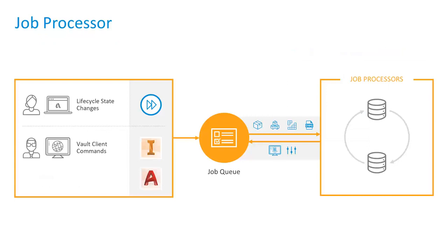The job processor is a separate application that reserves queued jobs and pulls them from the job server to process them. Since the job processor is installed among the Vault client, any workstation with the appropriate edition of Vault can be used to process jobs.